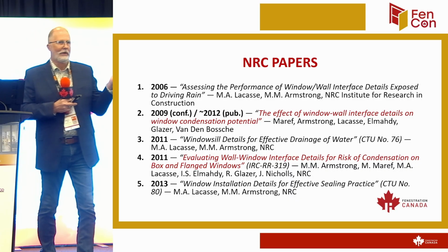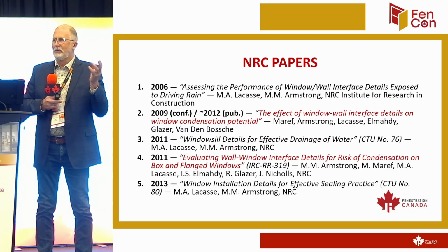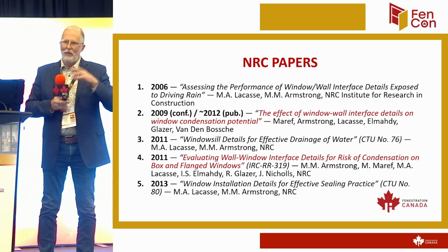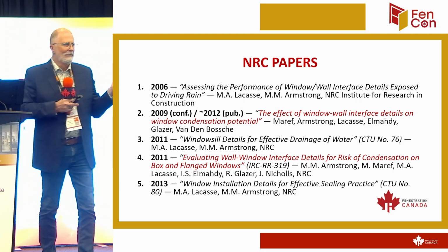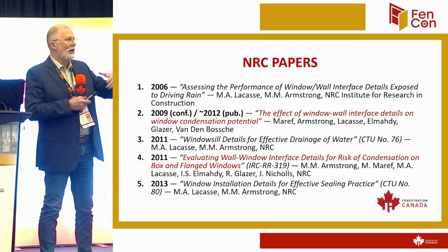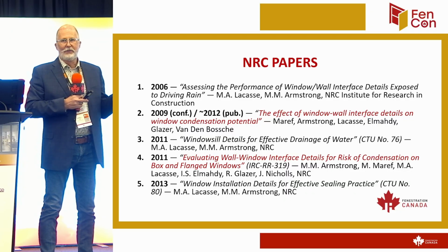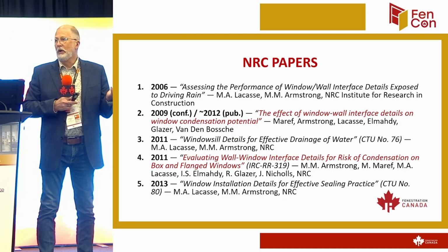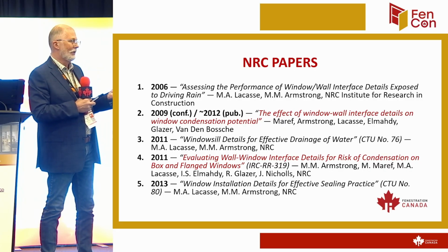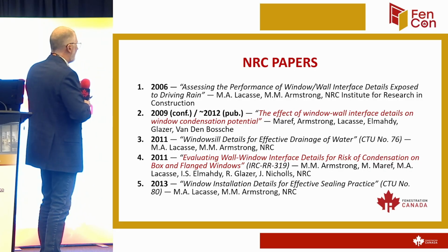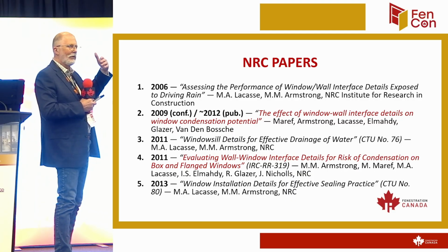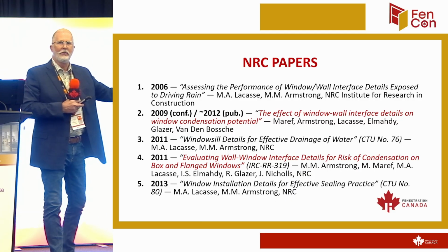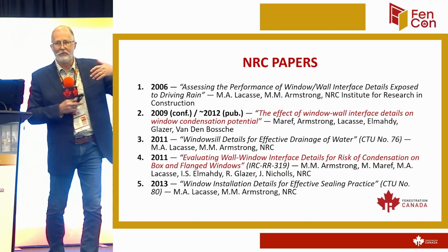There's no guarantee that water's going to get in there. This is not, don't use spray foam because it'll get leaky, and don't not put a sill pan in, because sill pans have been around for the last 25 years. They've been in commercial forever, but in residential, we haven't seen them a lot, but we also haven't seen the level of insulation and air tightness that we're seeing nowadays. So that's the downside of that. So we're trying to change the way we look at it and say, well, if we can't dry it out, we need to do something to keep it from getting wet in the first place.